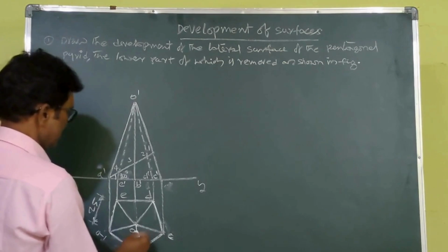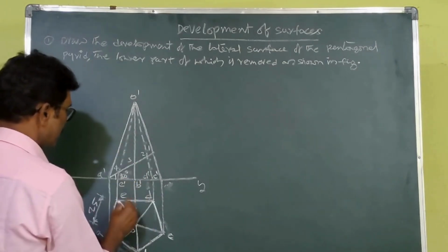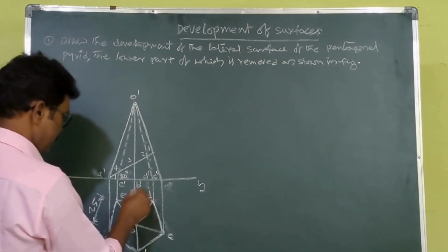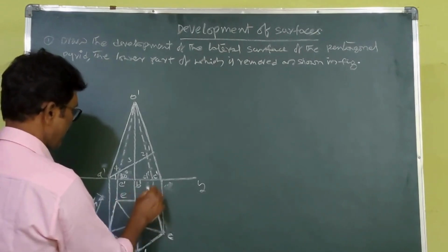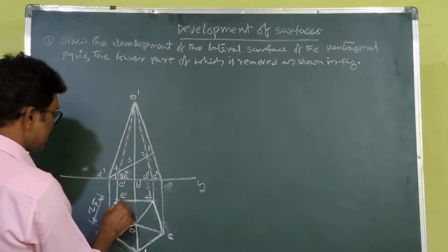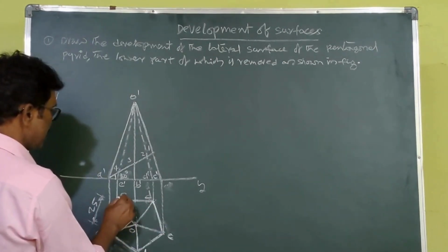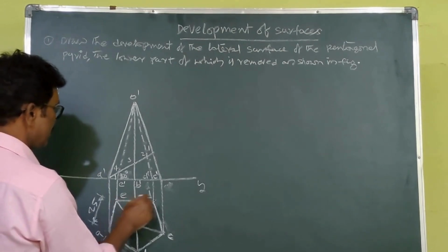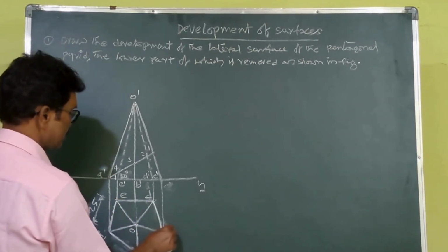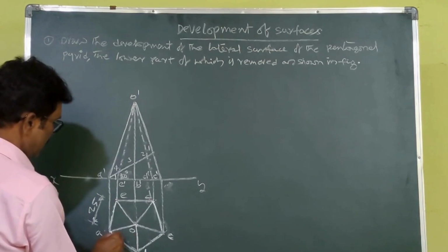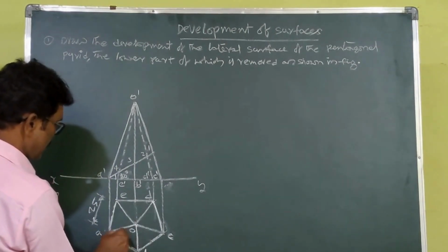the top view. So I briefly explain how to construct the pentagon, top view and front view. Horizontal line. According to the given problem, I am explaining. This is the 25 mm, XY, and parallel to XY you put 180 degrees. You draw the line, and with this as the center, E as the center, let us give the name E, D. E as the center, 25, you cut it. D as the center, you cut it 25, and at this point the same length. Of course, it is without angle setup.